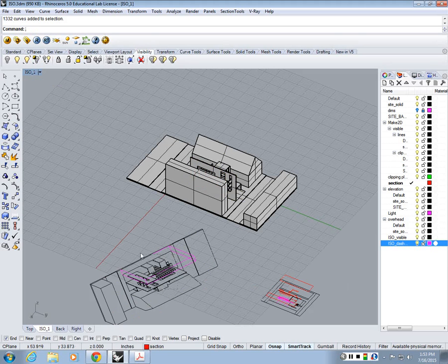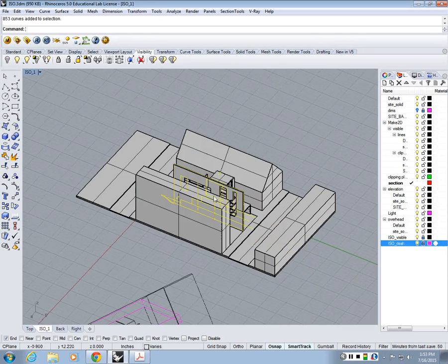But these are also curves, right? So they're like drafting lines. So I can lock these. Type in select curve. These are the ones I want to get rid of, because if you have curves in a drawing you want to do make 2D, you will also draft those curves, and you don't want to. You just want to draft the curves from solid blocks, like solid objects. Okay?